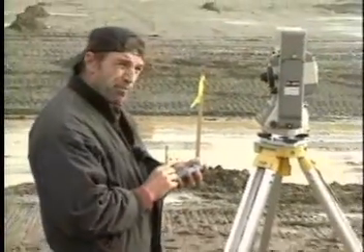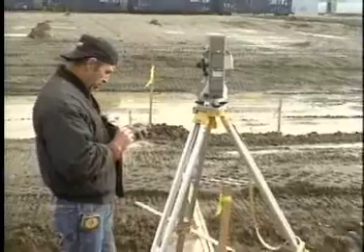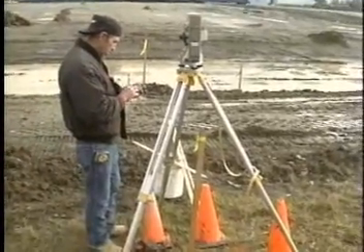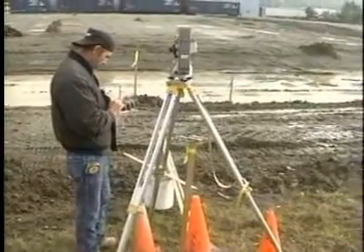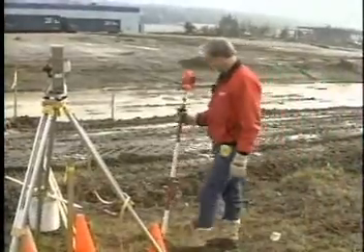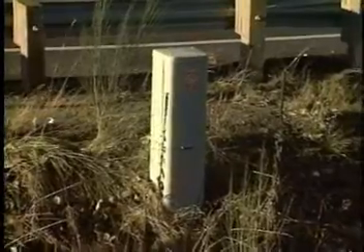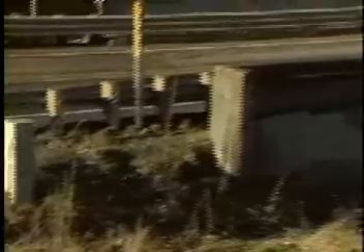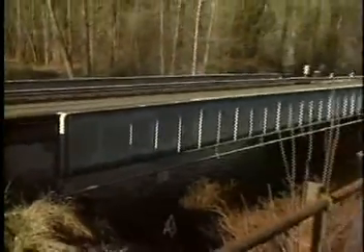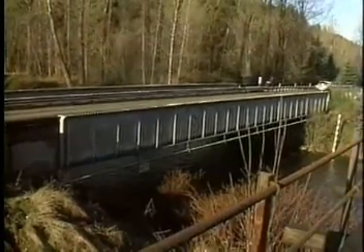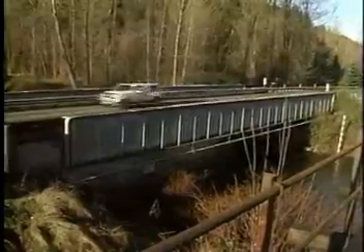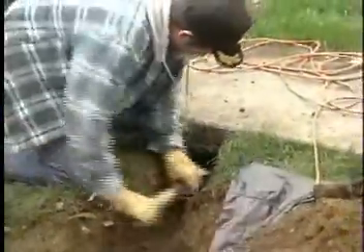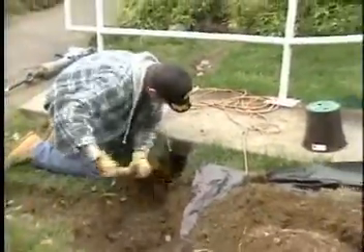The successful installation of underground cable depends upon careful route planning and engineering. As pointed out in our design video, a route survey addresses environmental issues, identifies all conflicts and obstructions, right-of-way access points, and repeater locations if required. The survey will also investigate soil conditions along the route to define the appropriate cable type, suitable installation methods, and depth of burial.